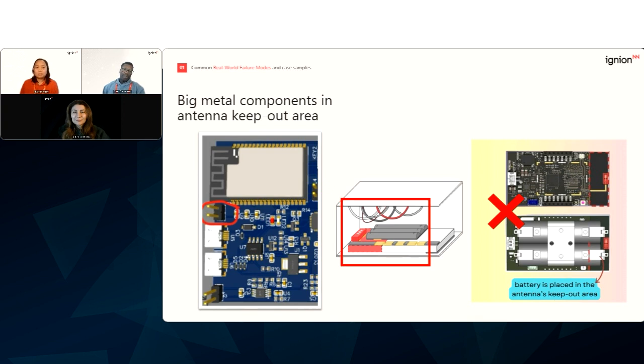And you could always test your device passively for impedance and get some decent performance, so to speak. But oftentimes, when you have wires sticking out, those also affect the active performance, because you have to worry about radiated spurious emissions, as an example, that impact your receiver sensitivity directly. So it's important to keep anything that could impact antenna performance away from the antenna.